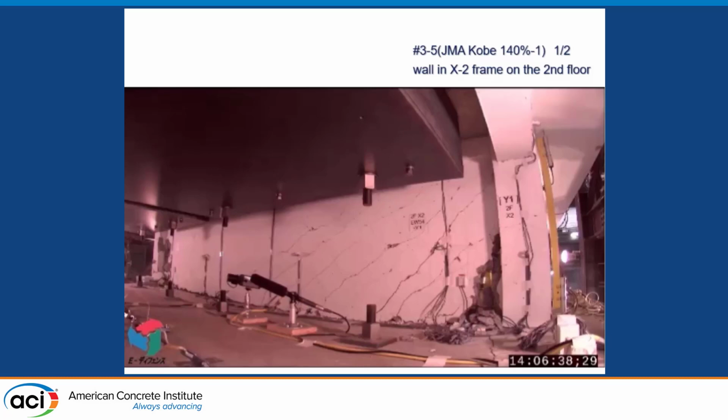Of course those walls failed in shear, but we had seen slippage at the bottom of the wall. After this shaking table test, we found that the boundary condition, or forces around the wall, should be considered.